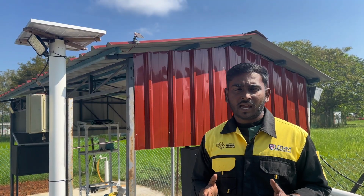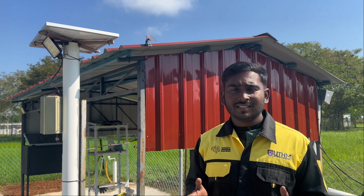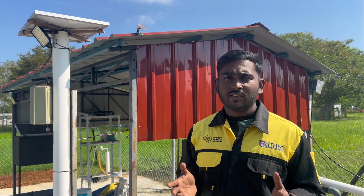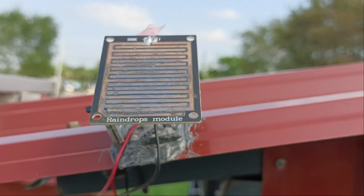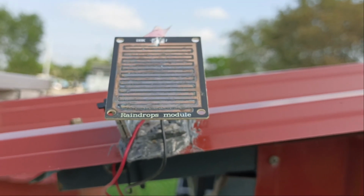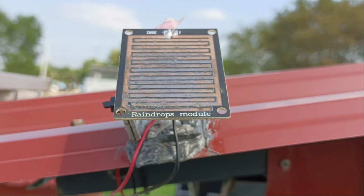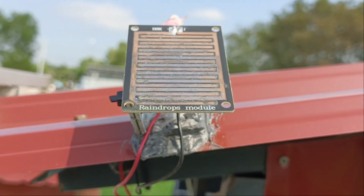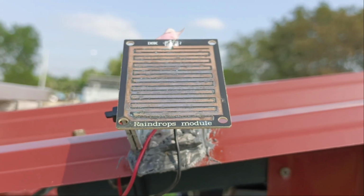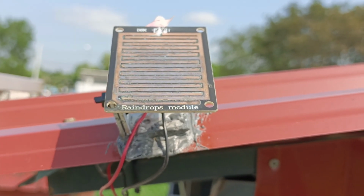In my cleaning system, I have integrated a rain sensor. This rain sensor is integrated to consider the real weather condition. If the rain falls, the system will skip. The rain sensor monitors the rain time on the natural time, which is from 12 a.m. till 7 a.m. If any rainfall happens between that time, my cleaning system will skip the activation because the rainfall itself has cleaned the dust or any debris on the PV panel naturally.